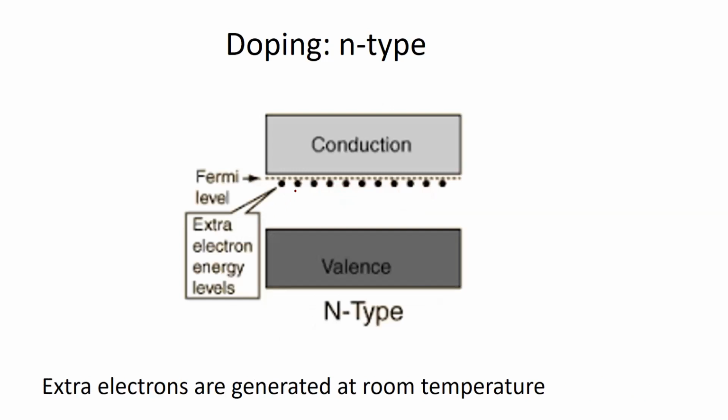Now, this is represented by the electrons from arsenic having energy states very close to the conduction band, as you can see them in here. And this shows that the energy required to raise the electron to the conduction band is very small. This is very different to intrinsic silicon, where the electrons would need to gain enough energy to cross its much larger band gap here. So that's obviously a larger amount of energy required. The same situation occurs with every arsenic atom introduced.